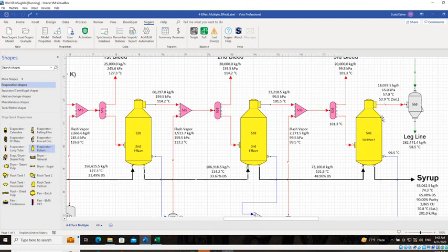Okay, so the question: HTC calculation for evaporators based on operating and physical parameters like temperature, brix, viscosity, etc., is not possible in Sugars. Why? Well, it says the formulas are pretty well known and already published many times, and that is true, but there's a lot more that goes into those besides just the temperature, brix, and viscosity.